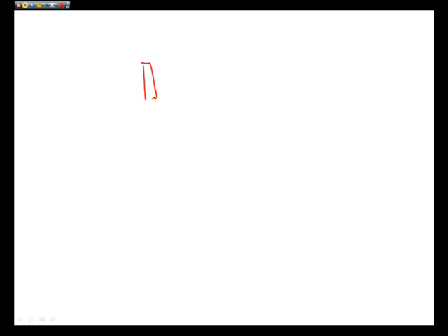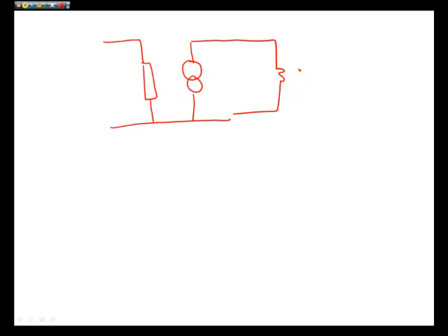Okay, so let's draw out the small signal equivalent model. Here's our transistor. Here's our standard output in RC. And here's this new component, and we're just going to call it RB as a first approximation. We have RBE coming in and IB.